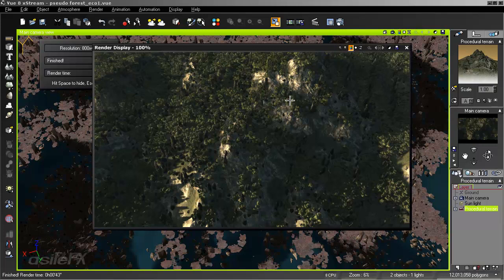Okay, I can tell that most of the conifers are under the terrain. So what I'm going to need to do is set up an offset and reduce that Z scale, because it is scaling from the pivot point, which is currently on the surface of the terrain. By reducing the scale and then increasing the offset, we can make sure that they're all jutting up correctly. The color looks like it might be a little red, so I might have to change the overall color within the ecosystem.